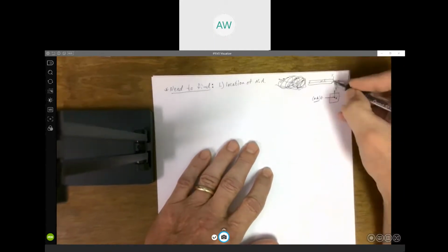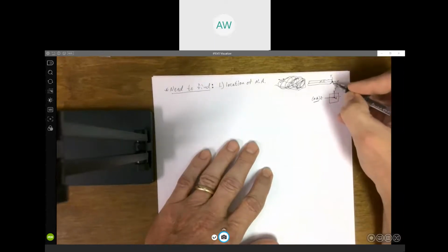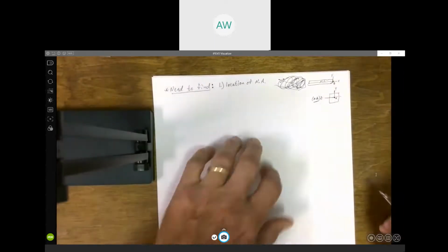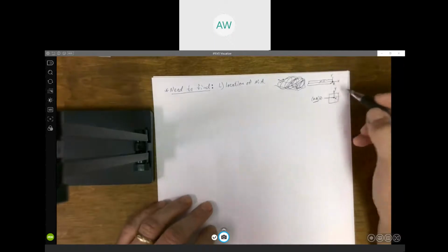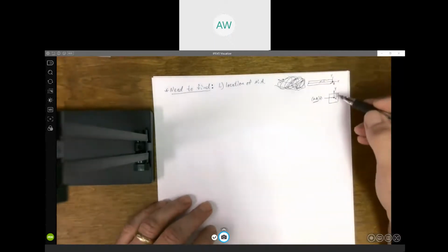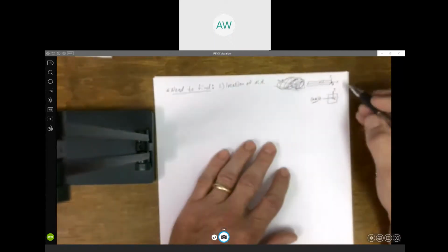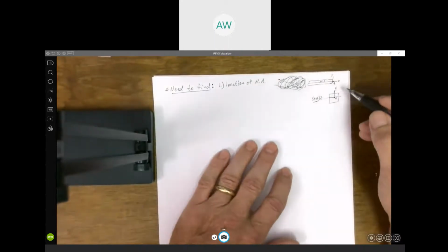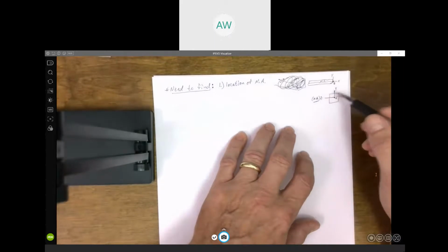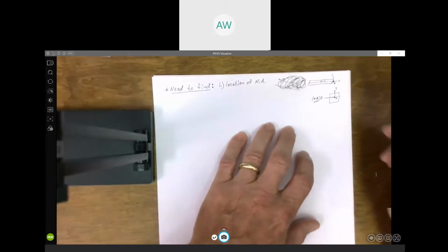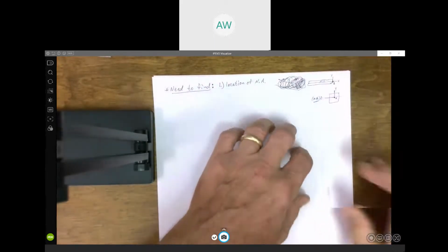It's going to correspond to here. z would be coming straight out at us. So when you're looking at the cross-sectional surface area, that's what we refer to as the neutral axis. Because if you remember, that formula was based on y, which y being the distance away from that neutral axis. Well, we got to know where the neutral axis is located. Otherwise, we don't know what y is. So that's one thing we need to find or determine.